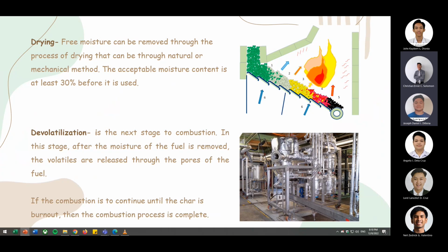The remaining particle after the combustion is ash. The mineral matter does not burn. Ash remains softer when the fuel is burned at low temperature. But for high temperature burning, the ash forms glassy spheres known as cenosphere. The formation of ash can cause slagging and fouling of the heat transfer surface.